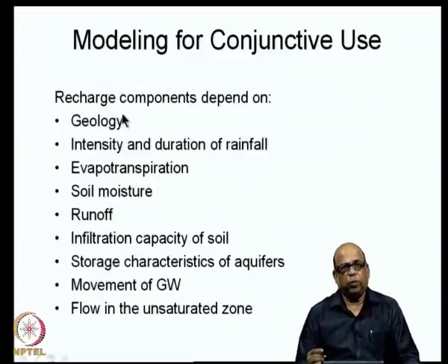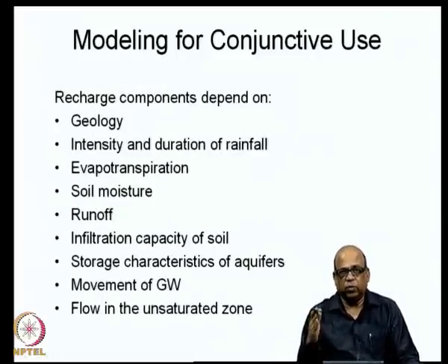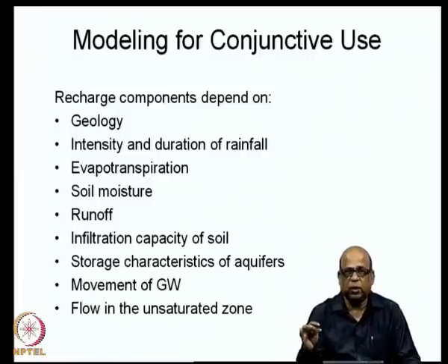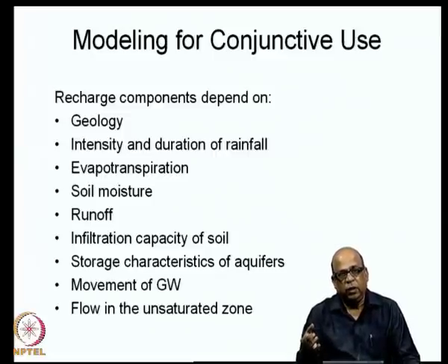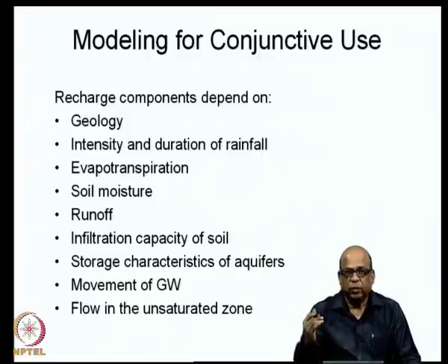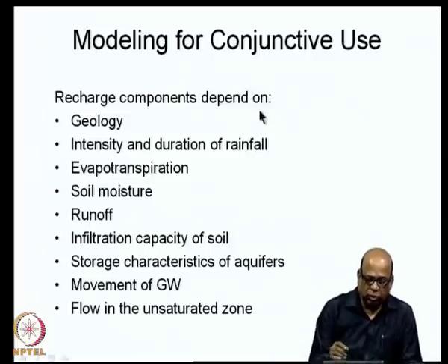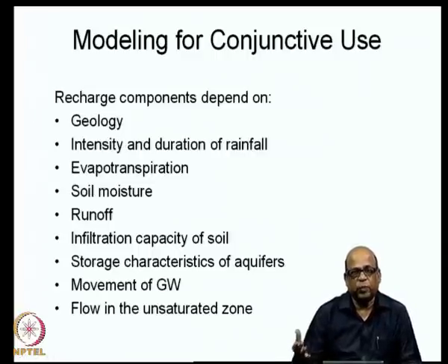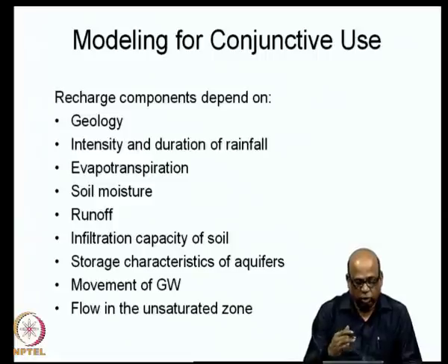Now, the recharge components that we are talking about, there are several recharges in fact. One is directly through the rainfall, another is what is applied on the irrigated area. This comes as infiltration, and whenever the moisture content below the crop is more than the field capacity, the moisture content in excess of the field capacity comes down as deep percolation, and we are assuming that all of the deep percolation goes as recharge. So, the recharge component depends on, first of all, the geology, what type of aquifer that you have. It may be hard rock or it may be alluvial and so on. So, it depends on the geology itself.